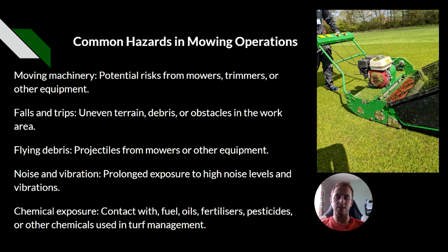Noise and vibration, which is a big one, can be split into two. Obviously, PPE with the ear defenders, and vibration. We are looking at things such as hand-arm vibration and monitoring how long we're using those machines, and that goes into monitoring the prolonged exposure to high noise levels and the vibrations to ensure we're staying within those guidelines. And this is part of a risk assessment.